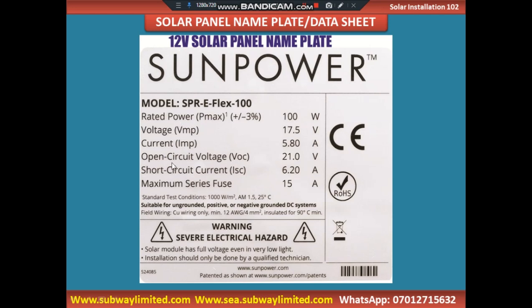But when you are talking about open circuit voltage, it is the voltage you have when you are not subjecting the solar panel to any load, and it is always higher than the voltage at maximum power, as you can clearly see here. This is 17.5 volts and this is 21.0 volts.